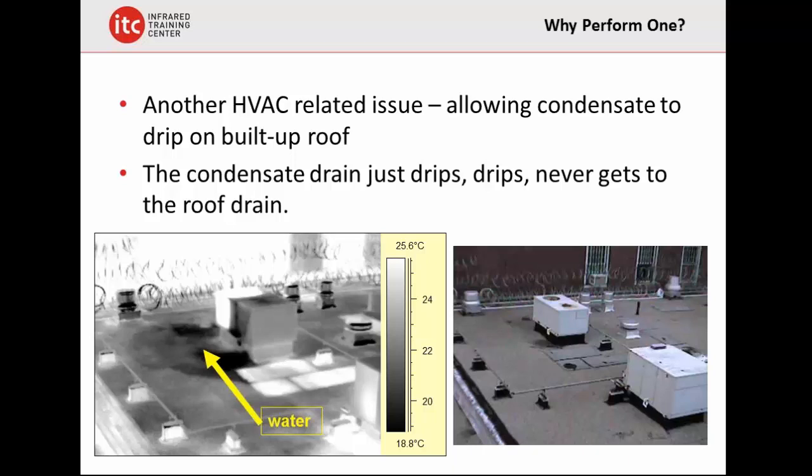The question came up with the gravel, Ron. How much gravel can you typically do an inspection through on a ballasted roof like this? I've done 6 inches of river rock. 6 inches? Wow. Heavy river rock over a membrane roof, like a plastic membrane roof. Now, that's not an hour after sunset, though. No, that was about 1:30, 2 o'clock in the morning. You have to be very, very patient.